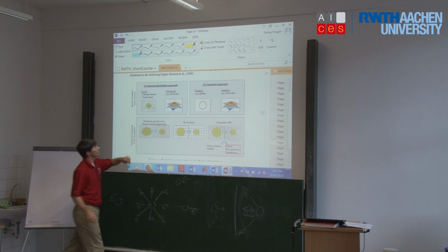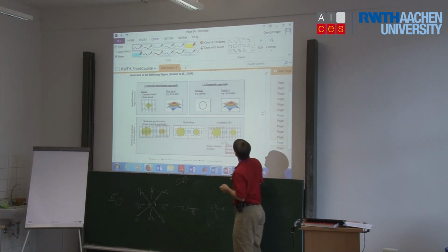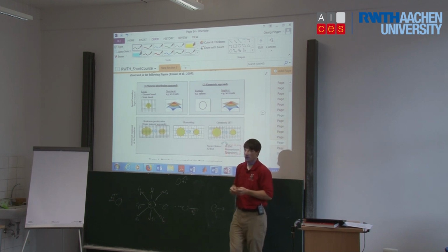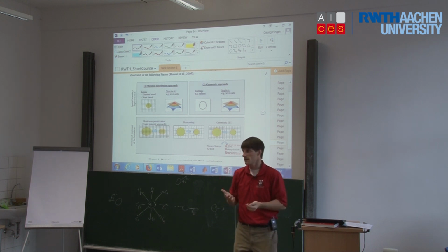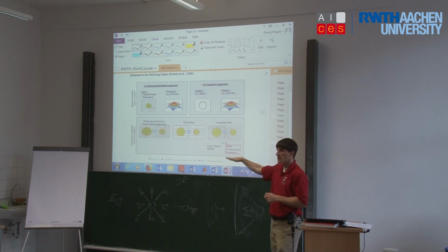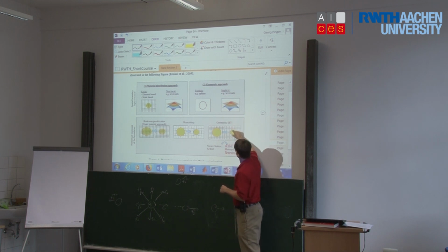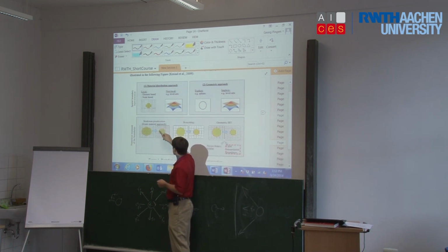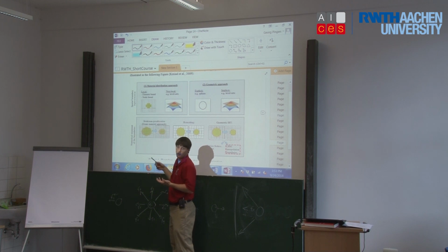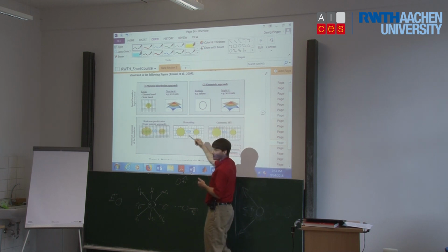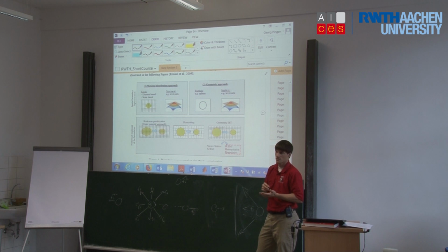Alternatively, we can use a more implicit approach, where we use level sets. So we use a higher dimensional function. If we're looking at a 2D problem, we usually have a 3-dimensional level set. So we have this mountain range, and we cut it off at some value. Slice it off. And wherever we slice it off, that's the geometry that we represent. Now we could take this slice and represent it back with the porosity-based approach. But alternatively, we can take this slice and do a body-fitted mesh. Typically, we don't do body-fitted meshes in topology optimization, because that would mean we'd be constantly remeshing.